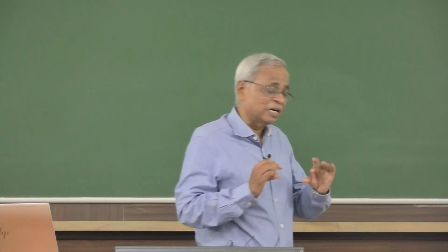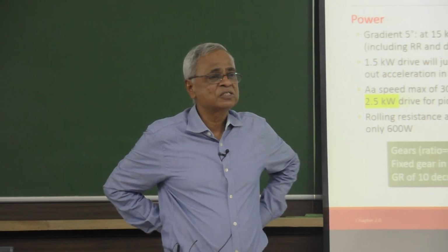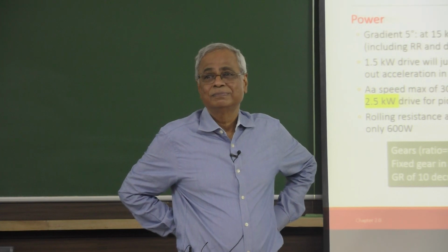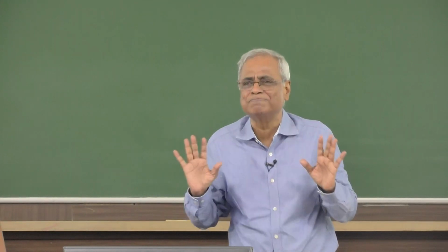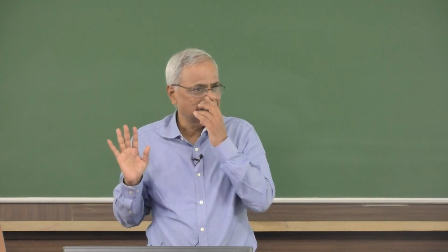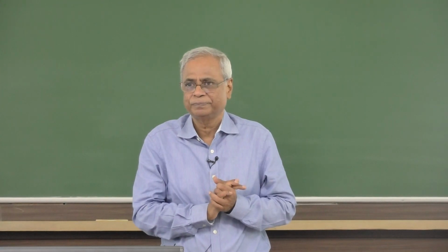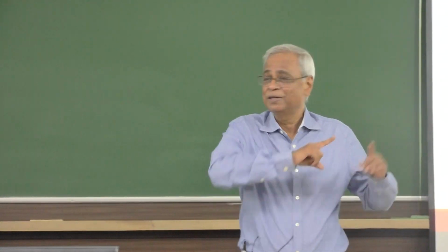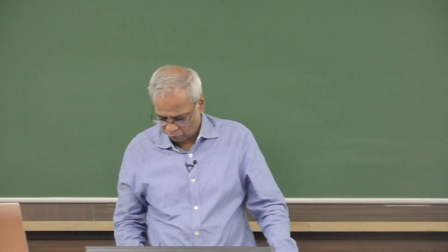The term used for gear, gearbox, clutch, everything in a petrol engine, IC engine, is transmission. Because you have a fixed gear in an electric vehicle, your transmission is very simple, a simple gear with a fixed ratio. In a petrol vehicle, it is far more complicated. Now, this however means that the motor has to be appropriately designed for a wide range of torque and RPM, and that is what we are going to focus on.